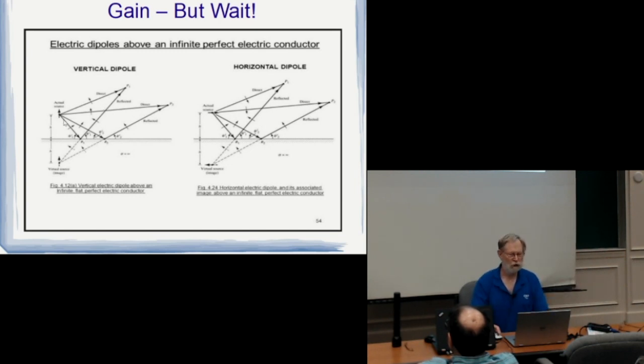So this is why vertical antennas, like a ground plane, are good for very low angle radiation. And in certain cases that could be DX, or for VHF it could be talking to the taxi cabs in town. So this shows that your choice of orientation immediately tells you something about your takeoff angle and what's going to happen at the horizon.